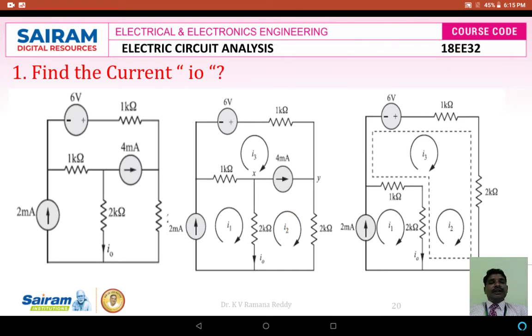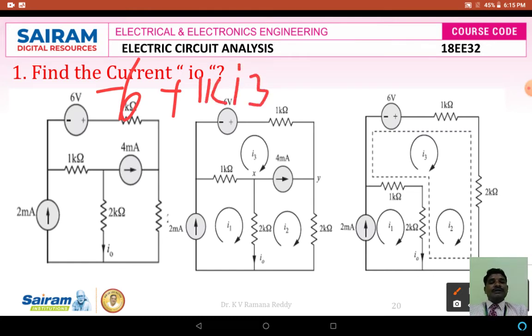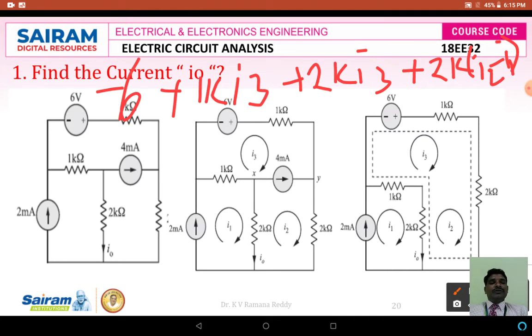While writing the mesh equation with KVL, the KVL equation is as follows: minus 6 plus 1 kilo ohm into I3 plus 2 kilo ohm into I3 plus 2 kilo ohm into I2 minus I1, because this 2 kilo ohm is located between the boundaries of two meshes, that's why two currents are flowing here.